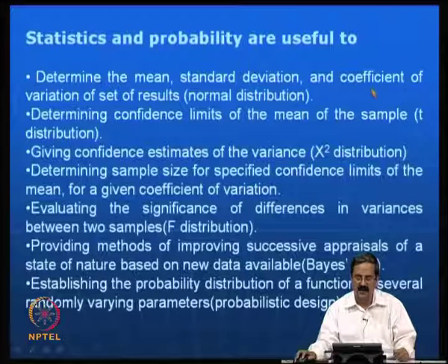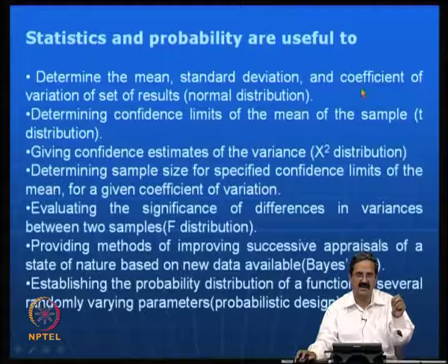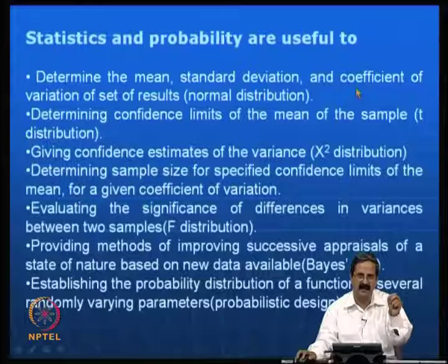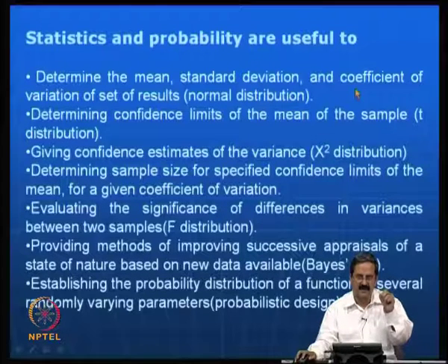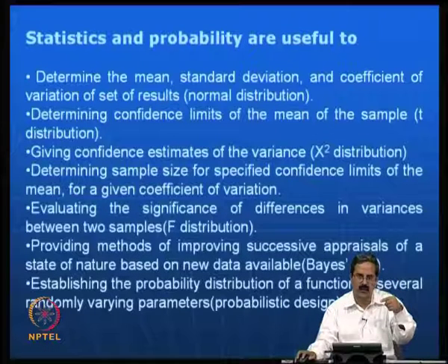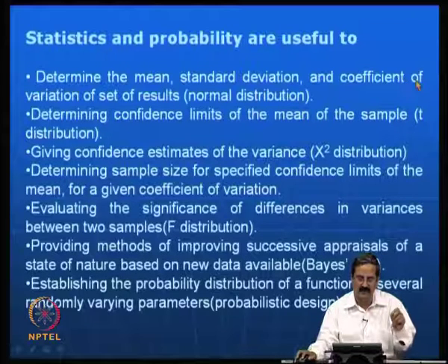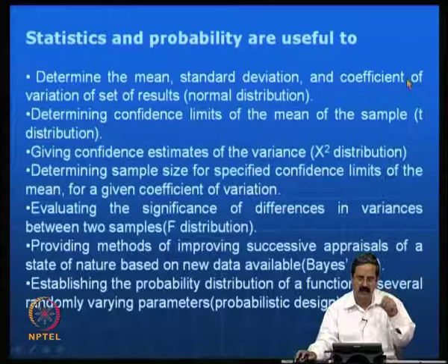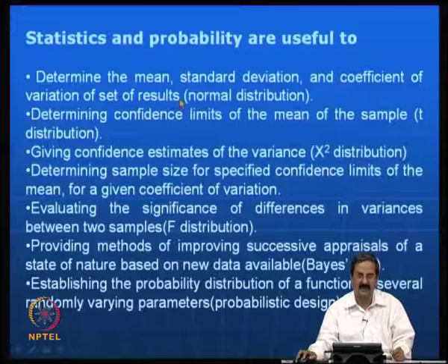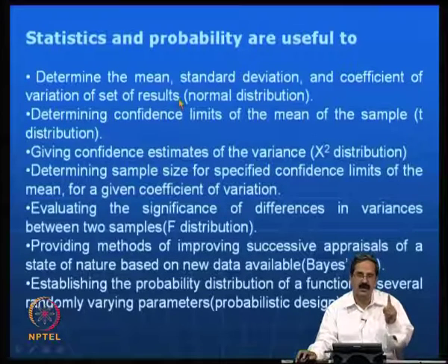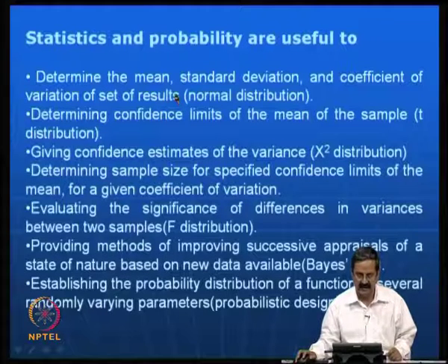We have the standard deviation. Say for example, the dry density is changing by 0.1; 0.1 is the standard deviation, and 1.9 ton per meter cube is the mean. So 0.1 divided by 1.9 gives you the coefficient of variation in terms of percentage. 0.1 divided by 1.9 into 100 gives you the coefficient of variation. So, you can say that I do not allow more than 10% variation. That is a very nice way of telling rather than telling anything.